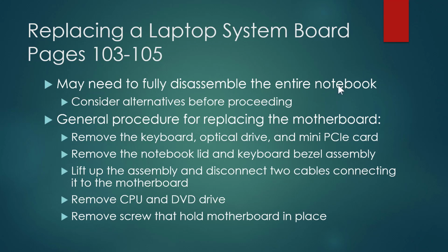You're going to have to take all the auxiliary components that connect to that motherboard off and out of the way. You're going to have to take the heat pipe assembly, the heat sink assembly out, maybe take out the memory sticks, take out all kinds of stuff before you can get that system board out, and there's going to be all kinds of screws involved that you need to keep track of.